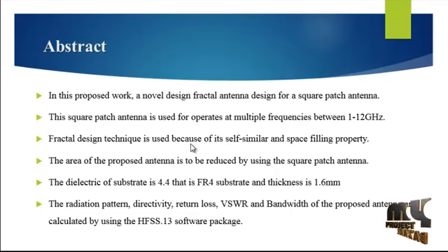The microstrip antenna basically consists of a radiating patch on one side of a dielectric substrate, which has a ground plane on the other side. The patch is generally made of a conducting material such as copper or gold, and it is very thin. The radiating patches may be square, rectangular, thin strip, circular, elliptical, triangular, or any other configuration. The radiating elements and feed lines are usually photo-etched on the dielectric substrate. The microstrip patch antenna is a low-profile antenna and has a number of advantages over other antennas.